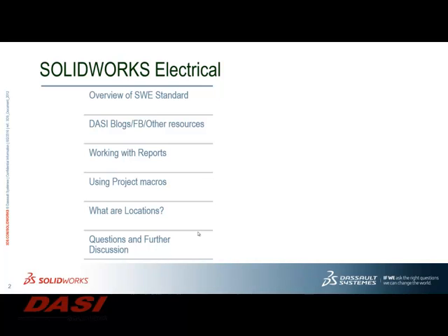And so immediately, because of that tag, when you go into 3D electrical, it already knows what 3D model it is, and because of the dimensions it readjusts it to that size, and then you drop it right into your cabinet. And because it already knows how it's connected up from your schematic, you simply do a 3D sketch to say, I want to follow this path, and it will follow that path to route that wire into that tube or that hose.